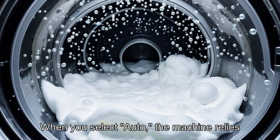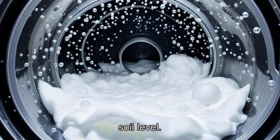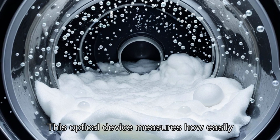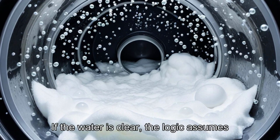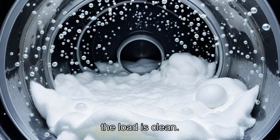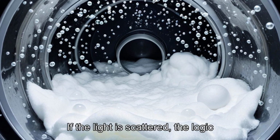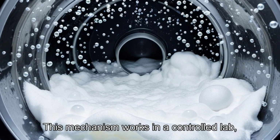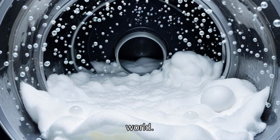When you select Auto, the machine relies on a turbidity sensor to determine the soil level. This optical device measures how easily light passes through the drain water. If the water is clear, the logic assumes the load is clean. If the light is scattered, the logic assumes the load is dirty. This mechanism works in a controlled lab, but it encounters variables in the real world.